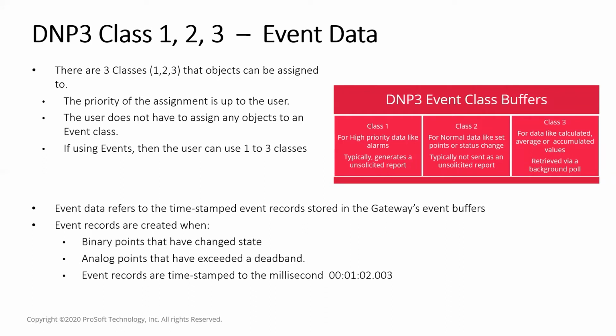And let's say if you lose communication to the site, then if you've got these as timestamped events, it's going to continue recording that data. When your system recovers, you're going to get all of that data back and backfill, which is why we say with DNP3, you don't have any holes in your data.